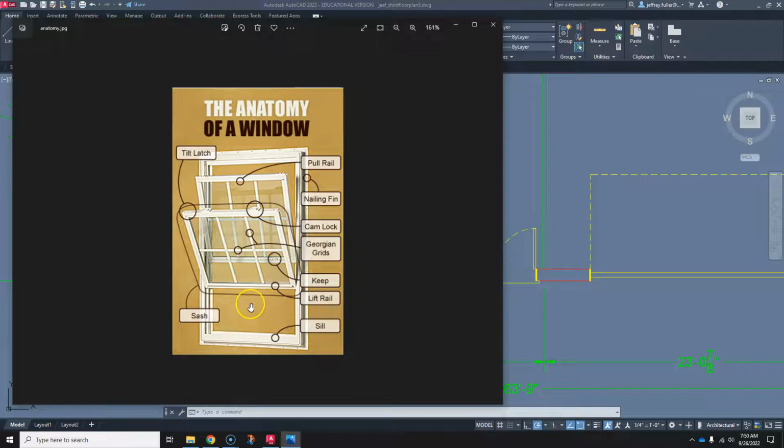But anyway, that 5.7 square feet of open space that they're talking about is the bottom portion right here. So even if you have a double hung window, or no matter what kind of window that you have, if it only opens on top or whatever, then that's not any good. We have to have one that opens on the bottom. This particular window, again, opens on the top and bottom, but the bottom is what they're measuring for that 5.7 square feet of open space. And that open space must be at least 24 inches in height, no less than 24 inches in height, and then no less than 20 inches width.